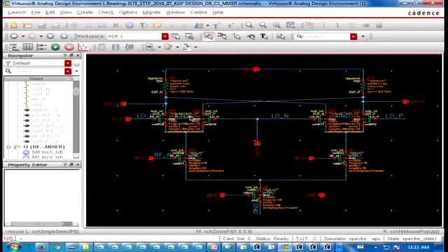Then we changed many things after iterations. So you have M1, M2, M4. M1, M2 drains are connected, M3, M4 drains are connected, they are cross connected. Finally, you go to the differential pair, and that is the RF in. So the main amplifier gain will be coming from these two stages.